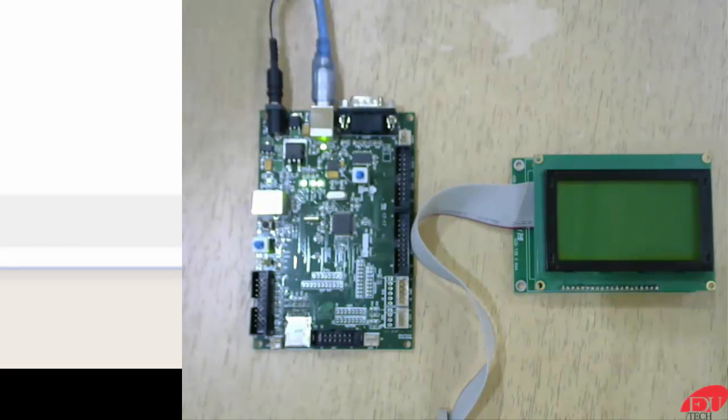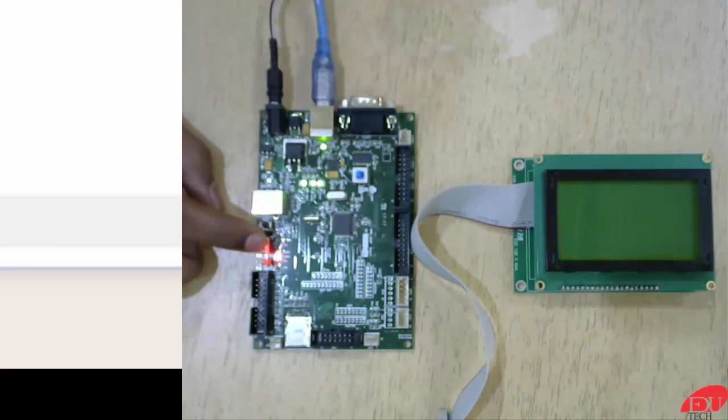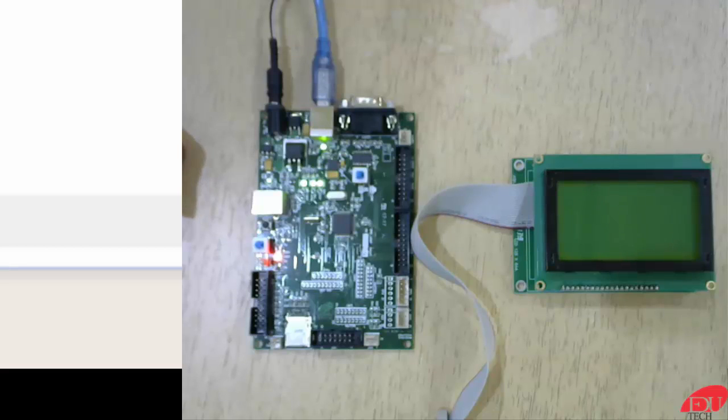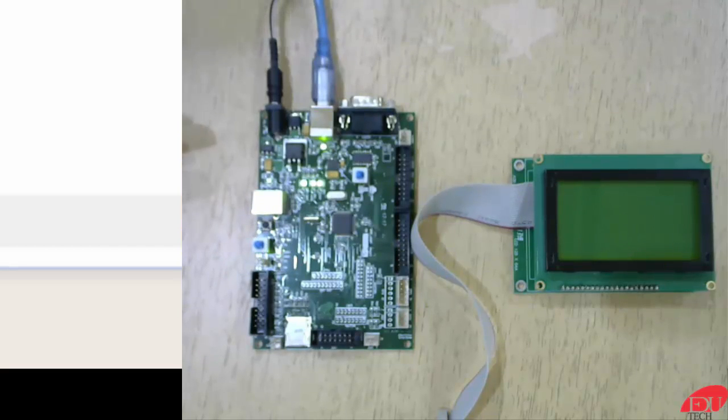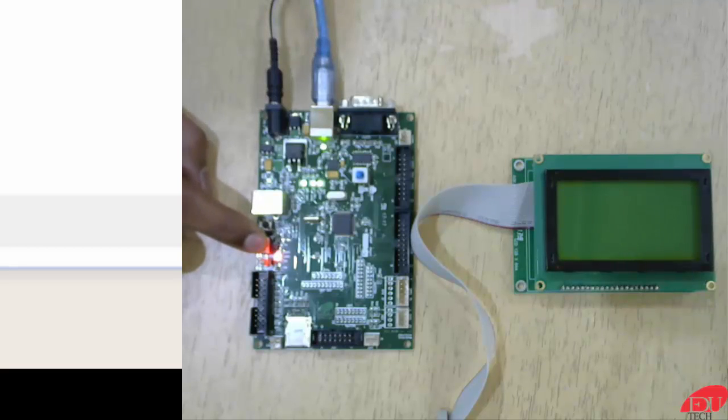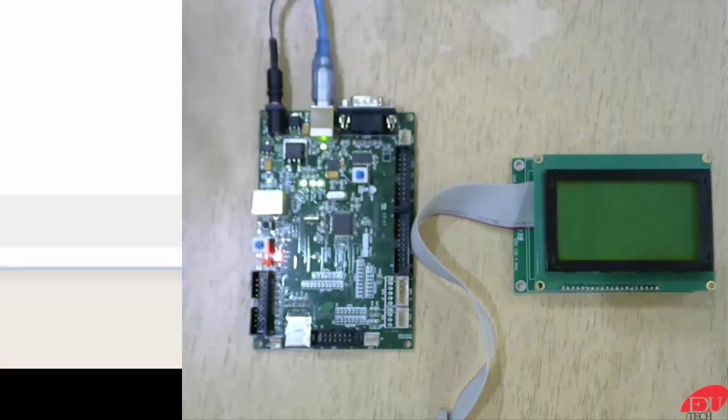Then after that, we have provided a DP/DT switch over here. If you press this DP/DT switch, then this red LED will glow, which indicates that the board is in ISP mode now, or in program mode. In this mode, we will flash our program onto this board, and in order to run the program, we have to unpress this DP/DT switch. Then the green LED glows, which indicates that the board is in run mode, and then our program is executed. So first we have to flash the program onto this microcontroller board. So we will press the DP/DT switch and we will press the reset button.